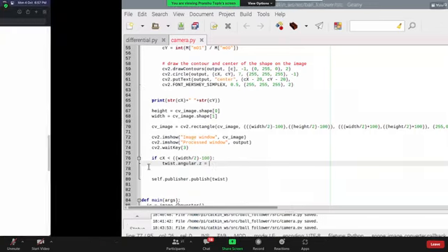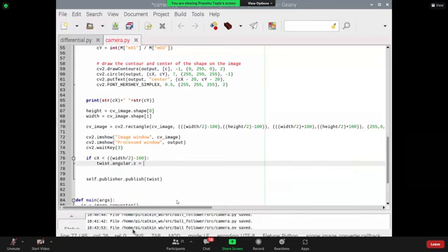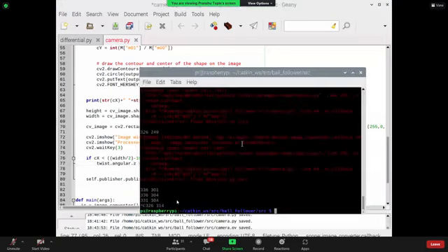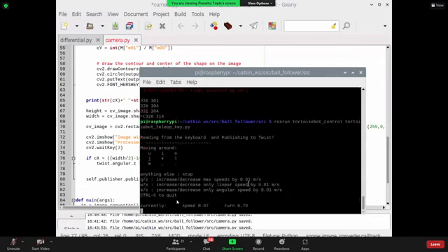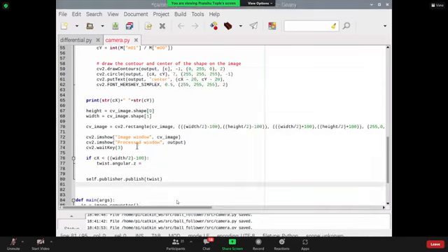The turtlebot runs at an angular speed of 0.7, I guess. Let me just check. ROS run turtlebot control turtlebot teleop key.py. Yes. So if we give 0.7 as the turning speed, it will rotate. So now let's give it 0.7 itself. So angular Z is 0.7.